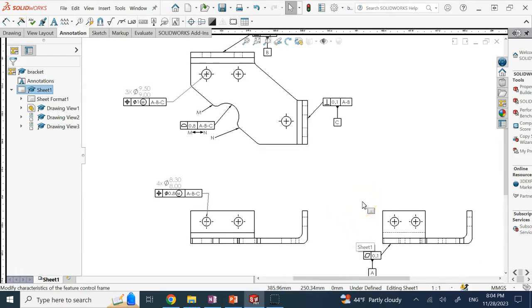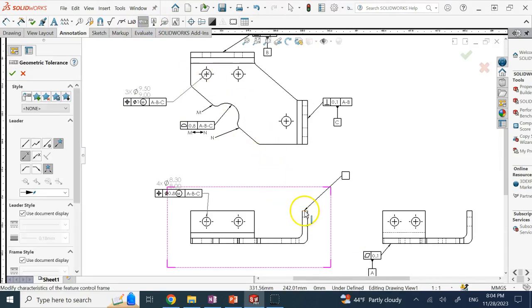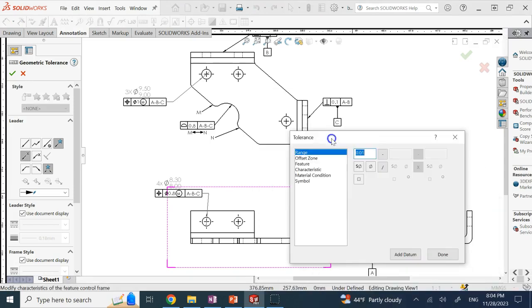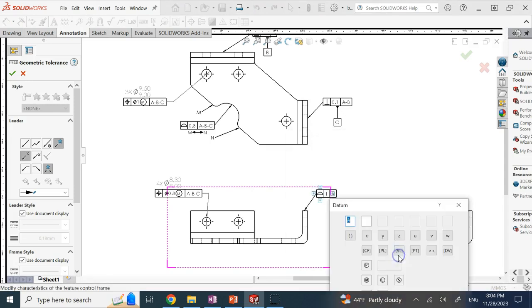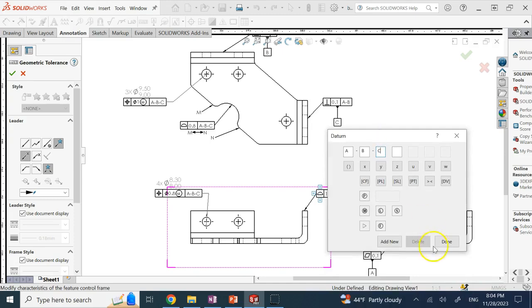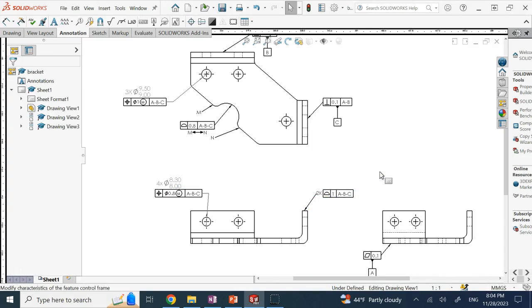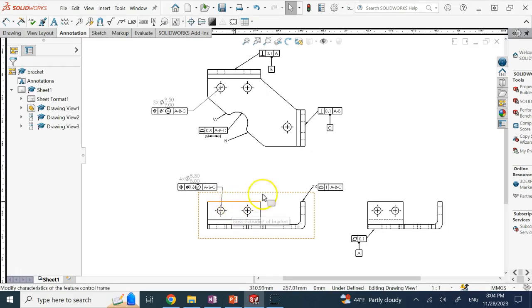Okay, so here we go, and now I'm going to apply a geometric tolerance here and make sure this is also a profile, and this guy is 1 with respect to A, B, and C, and pay attention that it's 2 of that. Okay, because you have it here on this one and you have it on the other flange. So you need to make sure here you say what? 2 times. Okay, it's 2 of that, and you have to pay attention to that part because it's for both of the flanges. Okay, now I got everything covered.